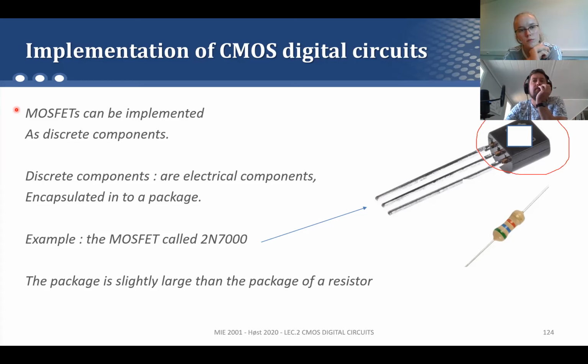And again, it might be a little challenging to understand the reason, because I have to explain analog things. But I just brought out these things to let you know that there are some packages of MOSFET which have 3 terminals rather than 4, and you should be aware of it. If you have any doubt, you open the data sheet of the component and look there at the meaning of these three terminals. Usually this one is the source, the middle is the gate, and this one is the drain.